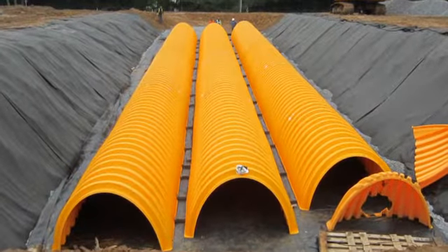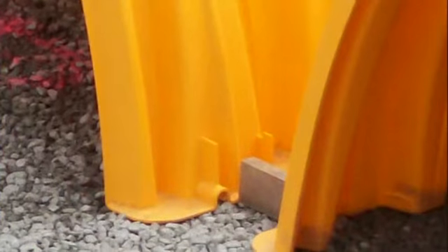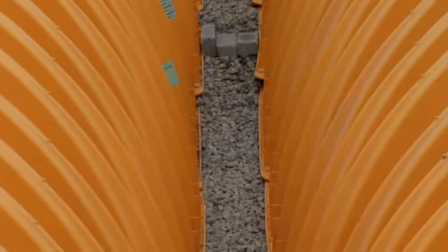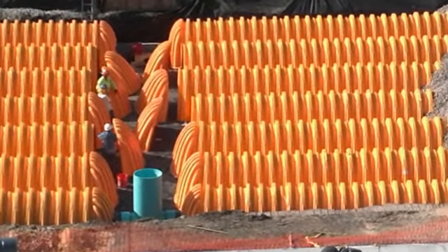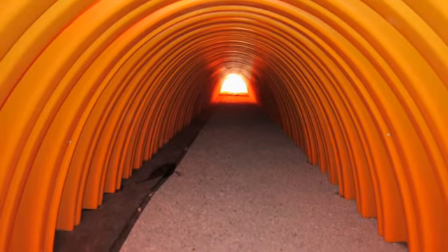In preparation for placing the chambers, a minimum 9 inches spacing must exist between chamber rows. Non-degradable spacers, such as brick, can be used for layout convenience. It is recommended that the end caps be left off of either end of the rows until the correct placement of stone can be visually verified.